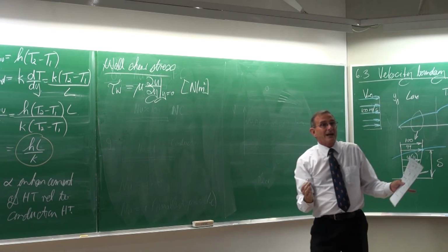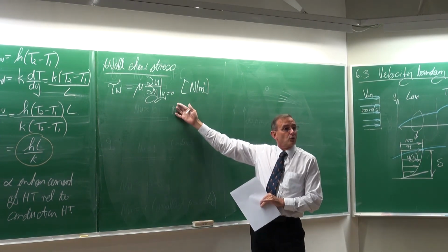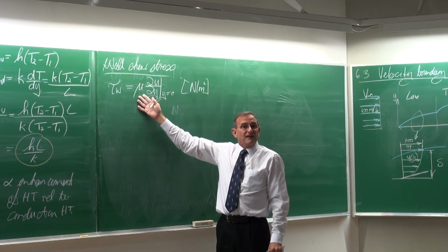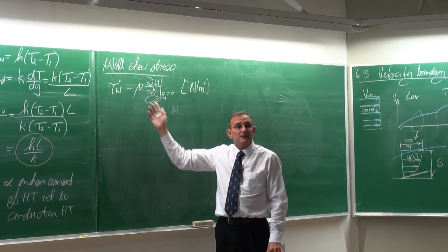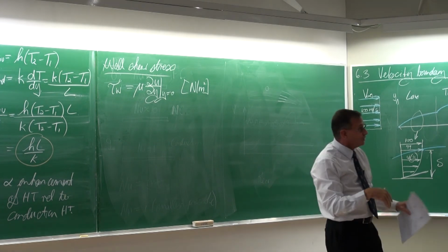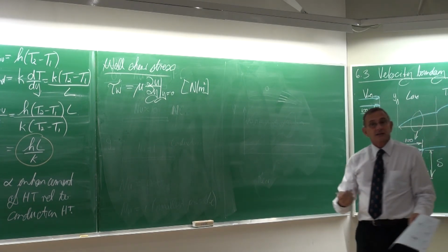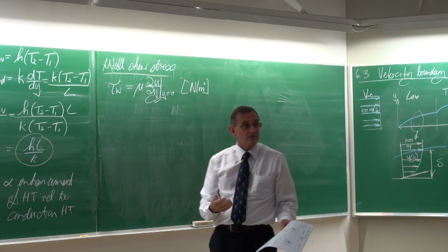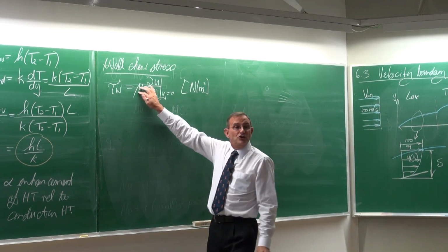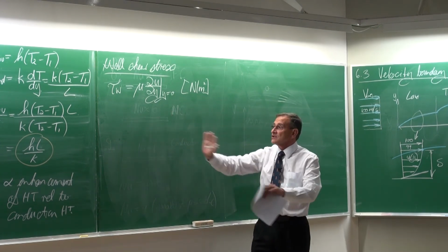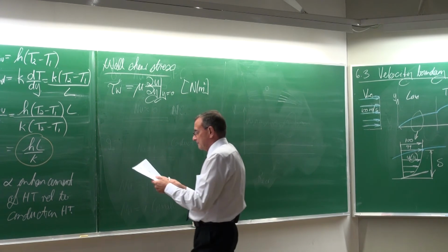Now in general, in mechanical engineering, this equation is always valid. It is valid for a Newtonian fluid, but there are also non-Newtonian fluids, and examples are blood and liquid plastics. For them, you need to use more complicated equations than this one. So this is for a Newtonian fluid.